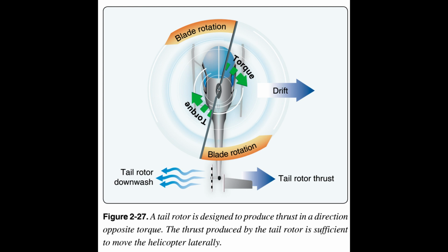1. The main transmission is mounted at a slight angle to the left, when viewed from behind, so that the rotor mast has a built-in tilt to oppose the tail rotor thrust. 2. Flight controls can be rigged so that the rotor disc is tilted to the left slightly when the cyclic is centered. Whichever method is used, the tip path plane is tilted slightly to the left in the hover. The transmission is mounted so the rotor shaft is vertical with respect to the fuselage. The helicopter hangs left skid low in the hover. The opposite is true for rotor discs turning clockwise when viewed from above.